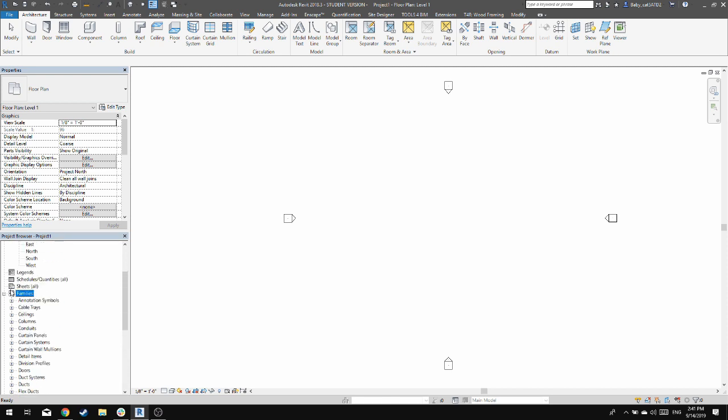This is something that I'll talk a bit more about once we get into stuff. And groups are things that you make locally in the project. So if you have a bunch of bedrooms and you want to copy a setup of beds between them, you can group it up and copy it, rather than having to manually place each of your bed and other furniture families in the environment.